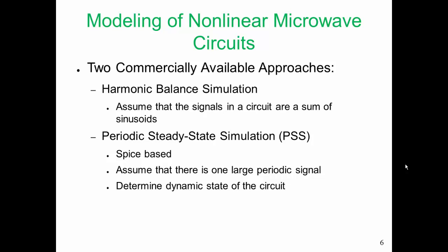We only need to solve it once up front and store the Y parameters of that whole linear circuit, but only at the interface points with the nonlinear circuit. With the nonlinear elements, we will have to consider them at every iteration in our analysis. So harmonic balance works extremely well when we have a large number of linear elements and few nonlinear elements.